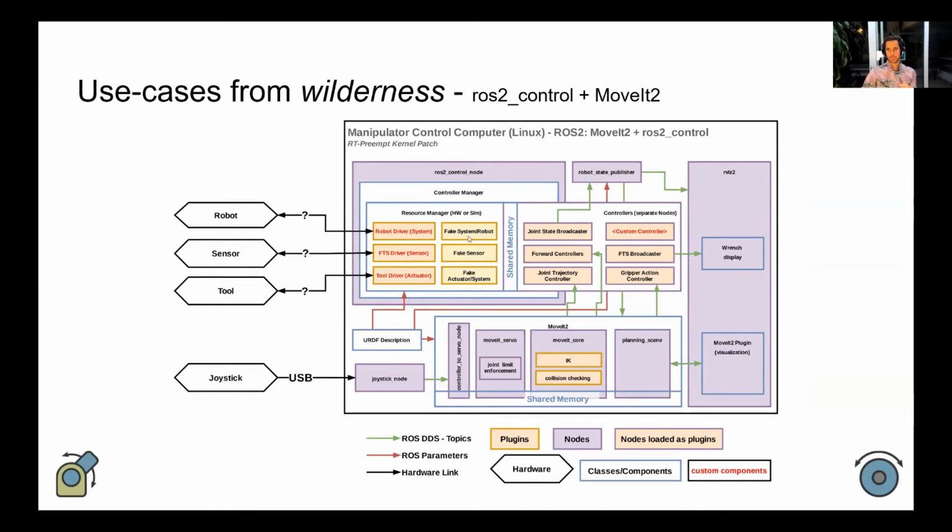I mean, for me, it saved a huge amount of time, because basically, without connecting to any hardware or any more complex simulation, you can simply test the complete framework. You can test if your controllers are switching properly, if your interfaces are accessed properly. You can visualize this simply. Basically, it's a very simple simulation without any dynamics in it.